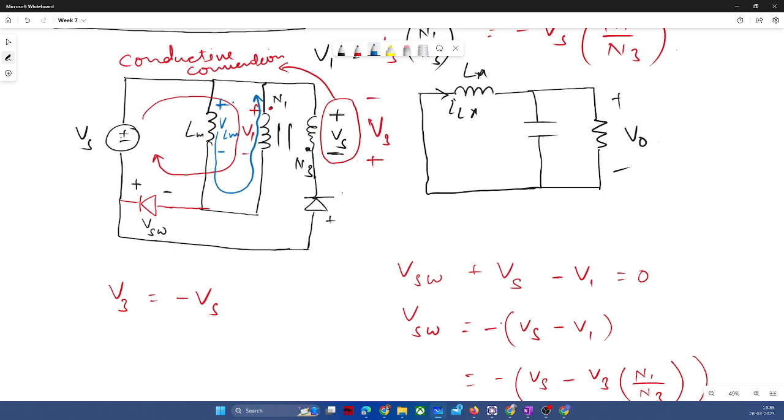It will flow through the tertiary winding. Yeah, you are correct. And no, it will go through the primary and tertiary. See, it will go through the primary and primary is indirectly connected to tertiary. So tertiary is there so that its current will be induced to tertiary. Our inductor current should induce to tertiary. Directly it cannot flow. Let me show you the equivalent circuit.